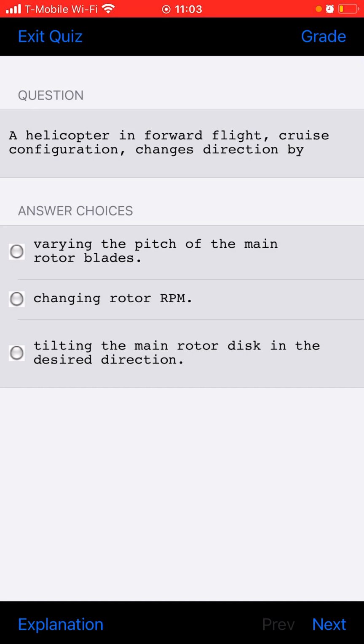If the travel of an airplane control is correct, but the cables are rigged exceptionally tight, what probable effect will this have when flying the airplane? The airplane will be heavy on controls.